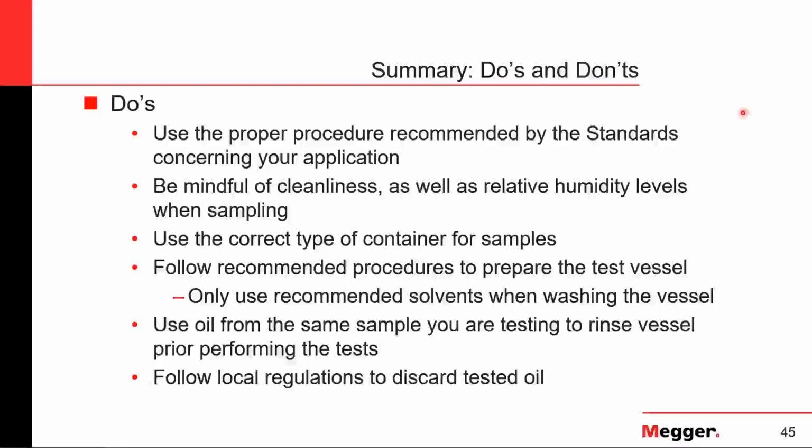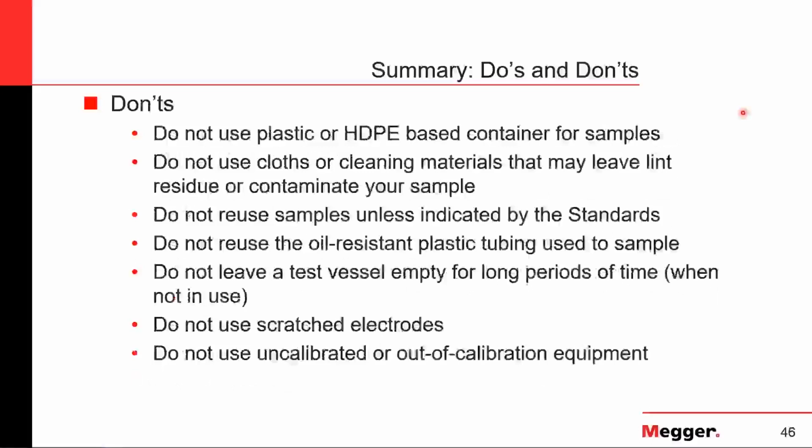Do not leave your test vessel or vessels empty for long periods of time. If you need to store them, make sure you have them filled with oil. Do not use scratched or damaged electrodes, or electrodes with carbon residue. Make sure you have good condition electrodes when performing your test. And do not use uncalibrated or out of calibration equipment.